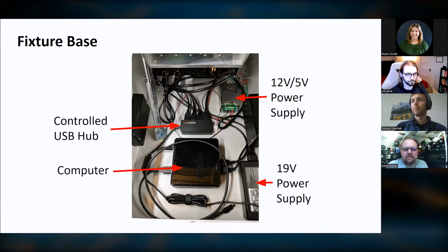Now, there are times I can imagine where I might want to take control of a certain net on the board. Would I do that with just some logic gates built into the circuit, like some AND gates or something? How do you go about doing that? Like if you're testing whatever, and let's say you want to intercept a clock signal, you don't want to send it to the microcontroller. You want to step through that on your own with the test specification. Is that something you guys help with, or is that up to the engineer to figure out?